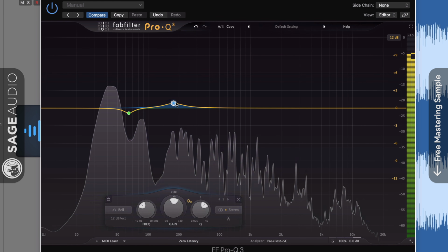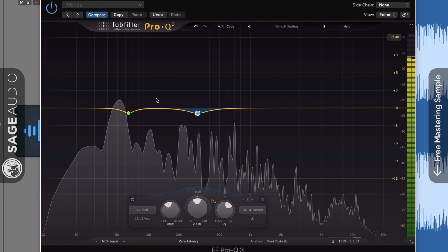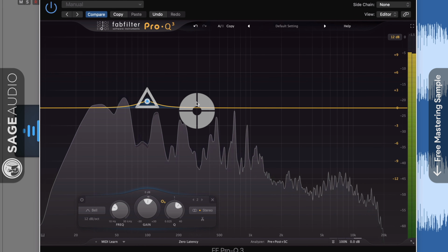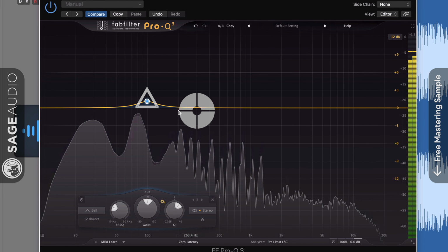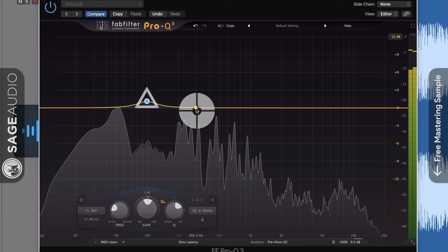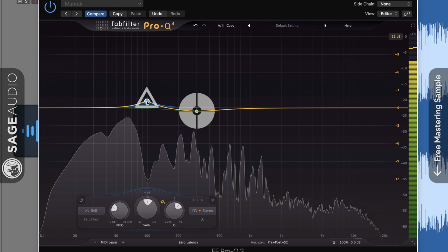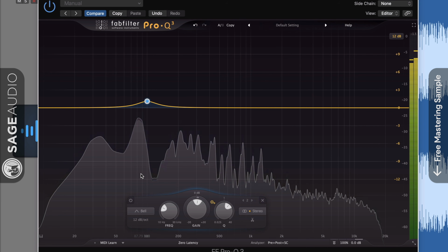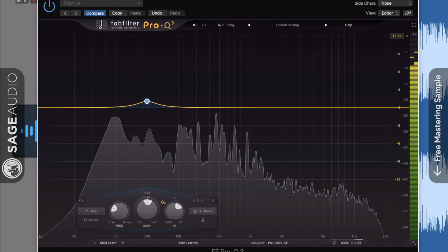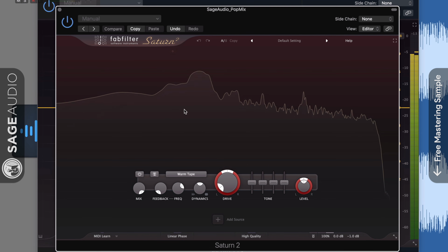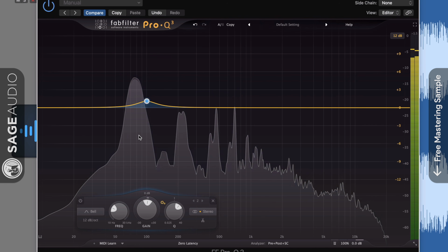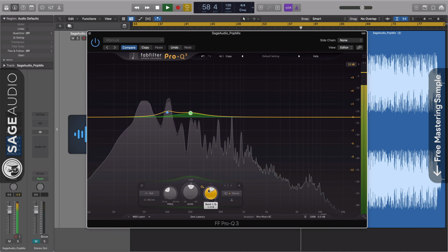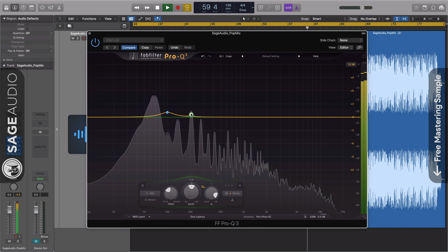This will make 100 Hz more prevalent without the two issues that we just discussed. Conversely, if we wanted a frequency to be less prevalent, say 300 Hz, we could amplify 100 Hz to make it less prevalent. In this example, we strangely get subtractive equalization by using additive equalization. Now, of course, this will make 100 Hz more prevalent as well, and potentially cause more aggressive processing from the next insert in your signal chain. Now, all of this is a bit complex and a little more advanced, but it's something to keep in mind when you're mastering and performing subtractive equalization.